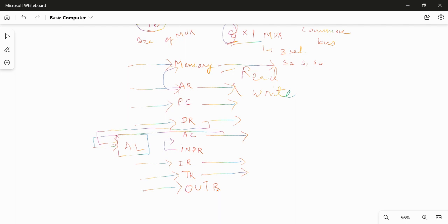Now, unary operations are also possible for most of the computers. So, for the basic computer also, if any unary operation, that means an operation that needs only one operand, is to be executed, then the content of AC can be used. In that case, no memory word is required to be accessed, no need to use even the data register. The content of AC will be used as the operand, and the result of the operation will also go to AC. So here the concept is that from the adder and logic circuit, the accumulator register receives the input.